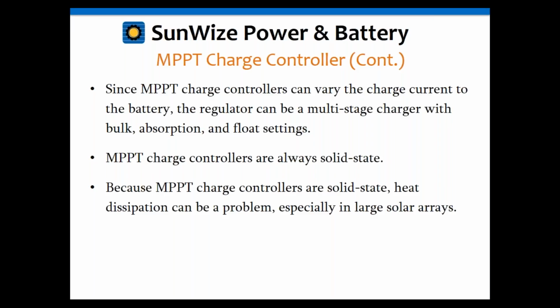And because of that, and even more so than the pulse width modulated controllers, because of the additional circuitry in there to store energy, they're going to run even hotter than the PWM charge controllers. You'll notice if you ever look at a PWM controller and an MPPT side by side, for the same amount of current, the MPPT has quite a bit larger heat sink, and that is because of that. So it has to dissipate even more heat out of the unit, and you might want to think about that when you're working with a large solar system, that you have additional heat to deal with, and you have these large controllers that you need to install somewhere.